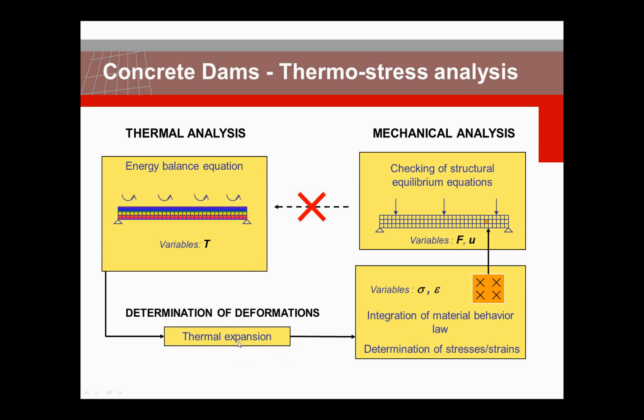So we account for the thermal expansion. That means we have a thermal expansion strain prescribed in the elements, which we will balance with the boundary conditions and the external loads that are applied, such as the hydrostatic load and the weight load.